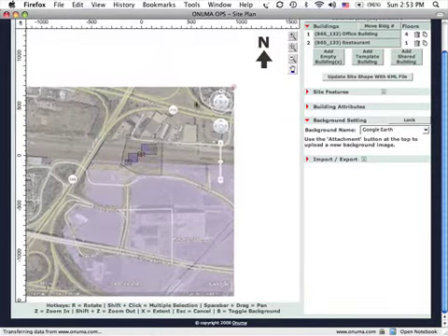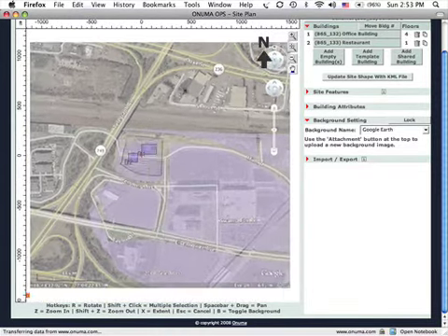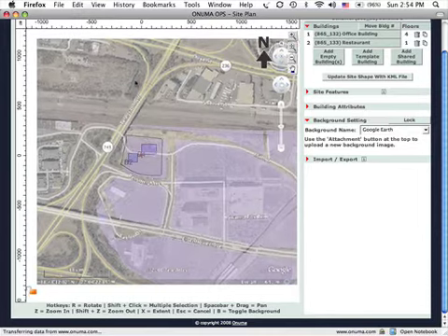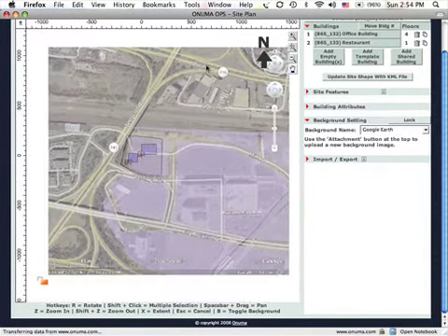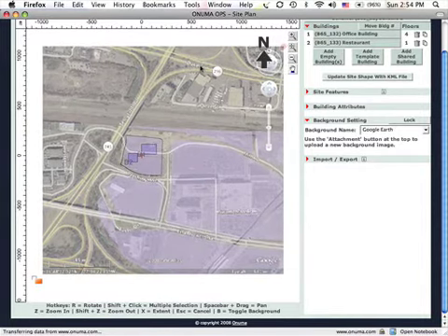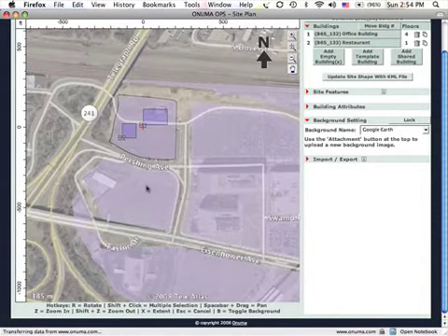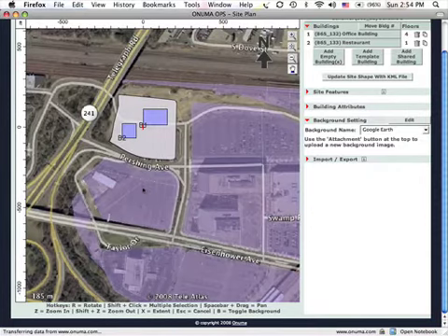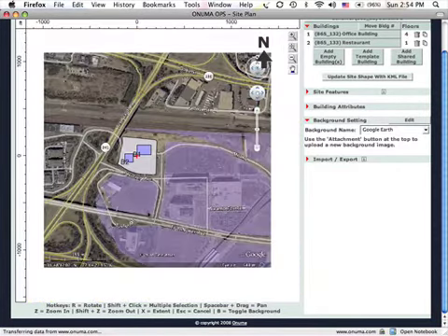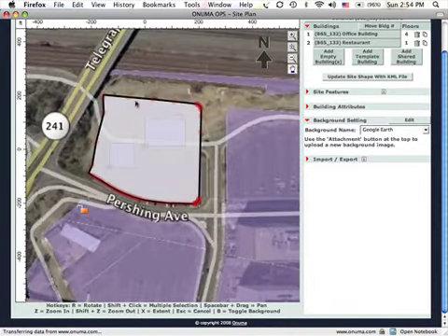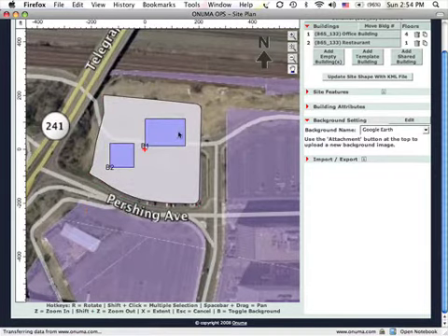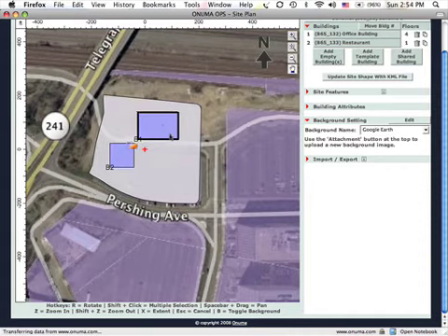It could be any element in an image like this. You could have a scale that you can align with the scales at the top, or you can graphically get it to the right size by continuing to do this. So let's say that this is within range. And if I hit B again, then it goes back and locks the background, so I can no longer grab it. So now these buildings are sitting on the actual KML file that came from Google Earth, the property line, the image in the background, and the buildings are actually elements here.